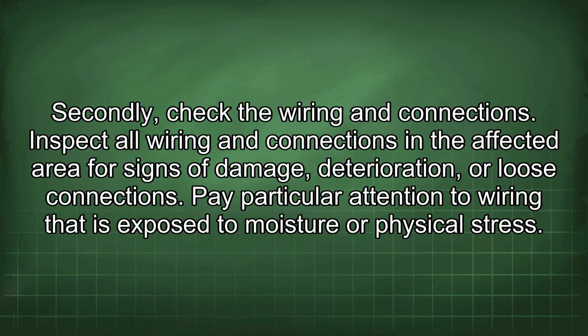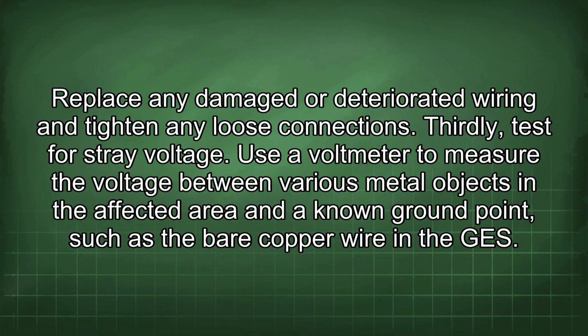Secondly, check the wiring and connections. Inspect all wiring and connections in the affected area for signs of damage, deterioration, or loose connections. Pay particular attention to wiring that is exposed to moisture or physical stress. Replace any damaged or deteriorated wiring and tighten any loose connections.